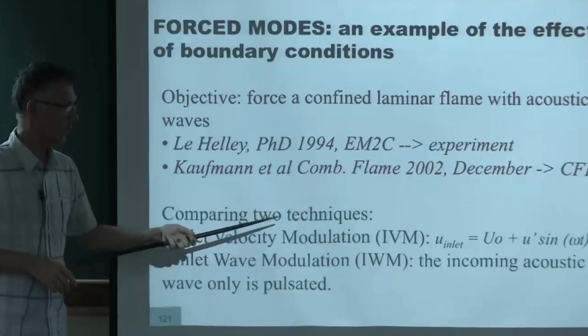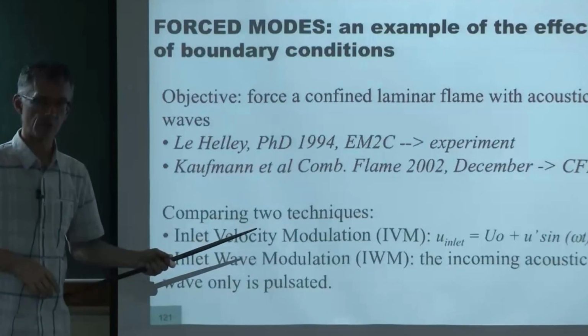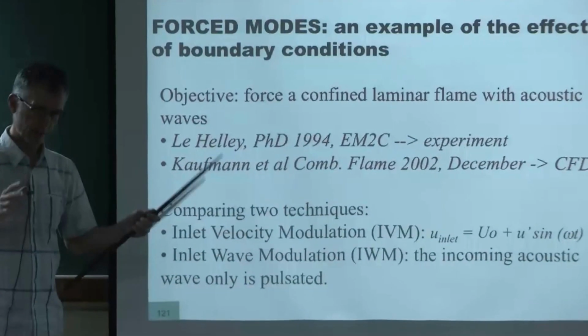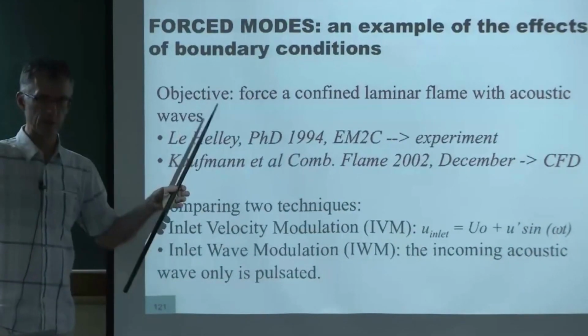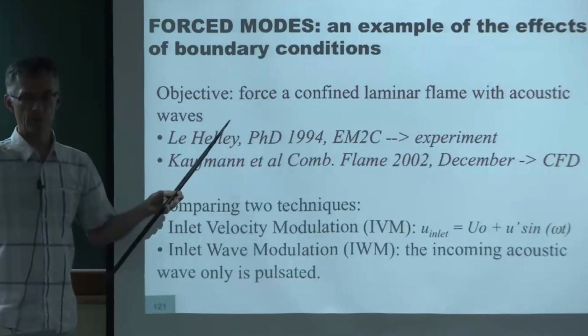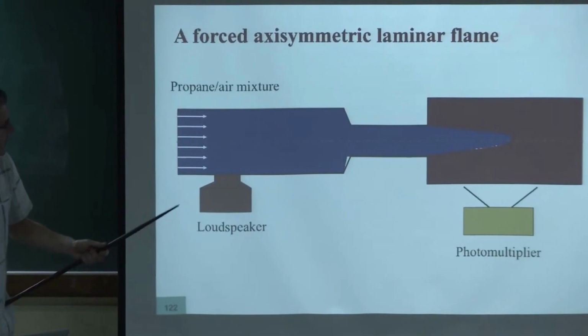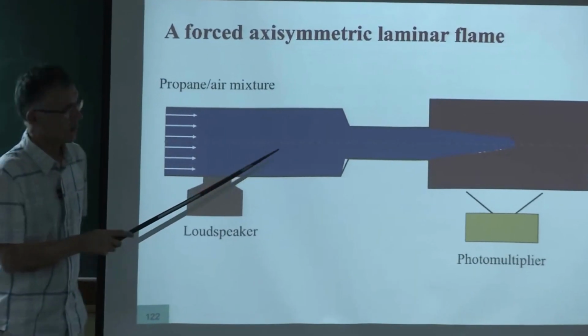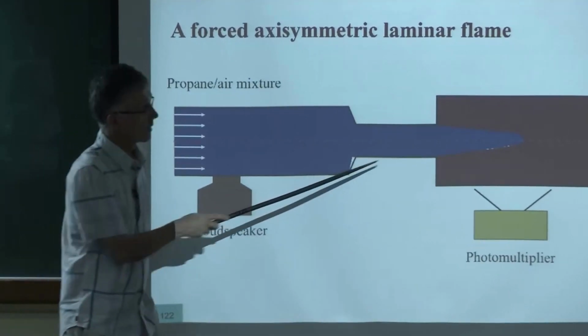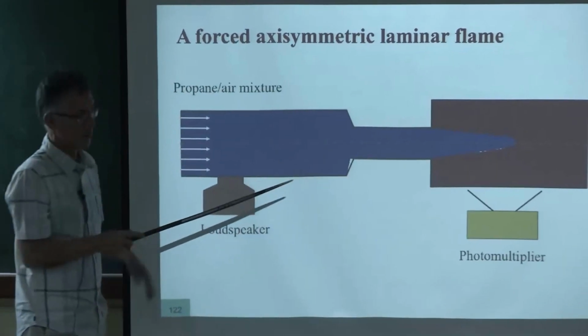In that case, if we do this method here, we don't have to change the geometry. So we can stick to the same geometry, we just make the boundary conditions different. We make them non-reflecting. Let me give you an example. So we take this case, okay? That's a simple one. That would be the same as the experiment. That's the Bunsen flame. Here you want to introduce waves.